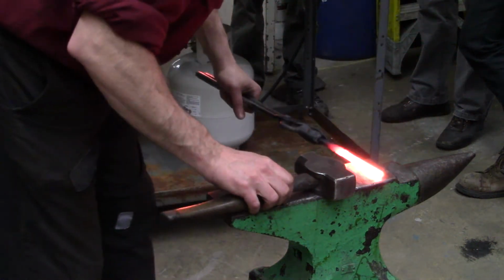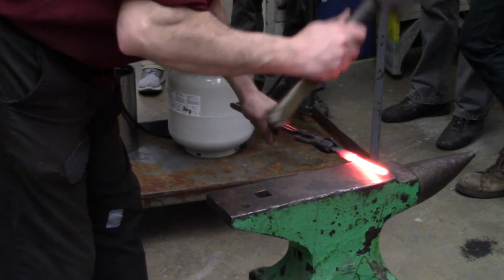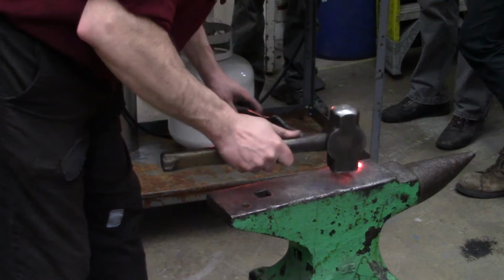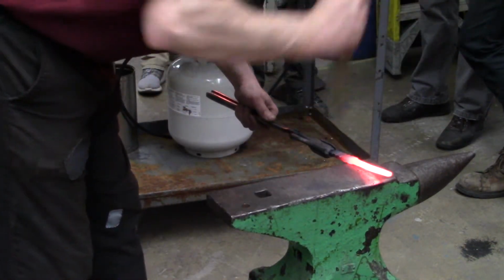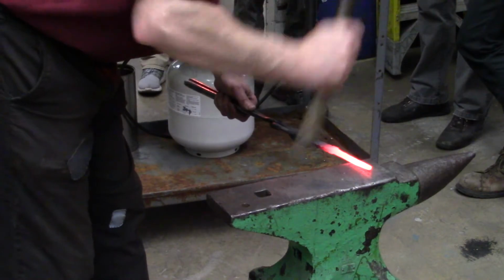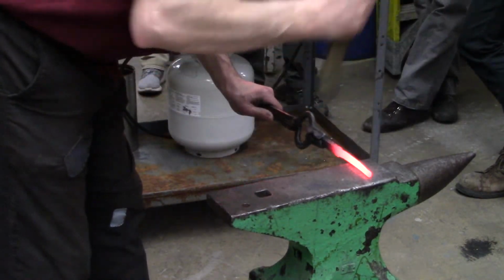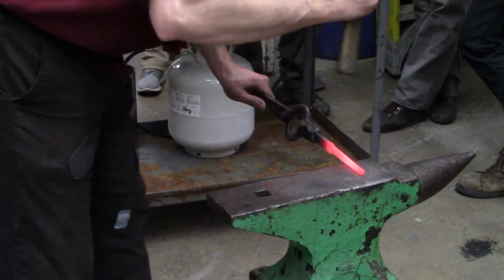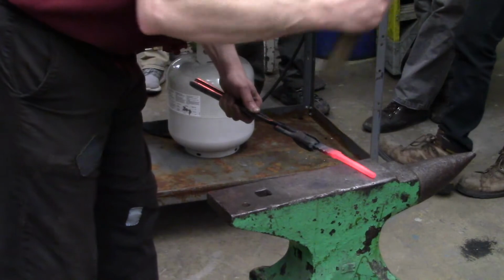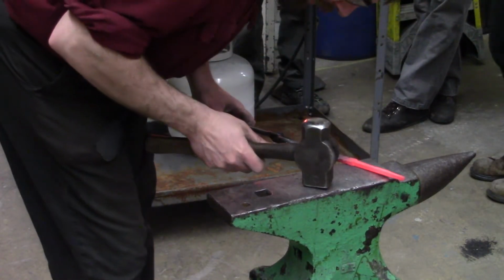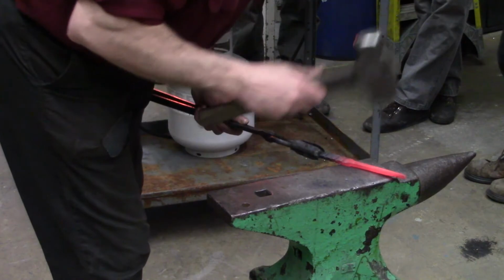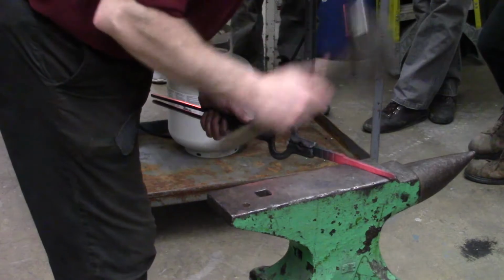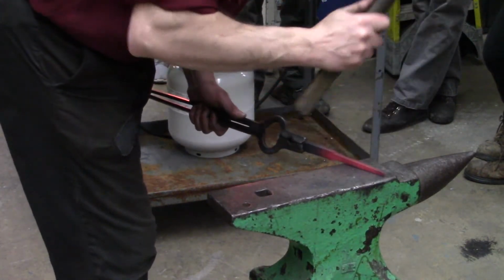The nut that you put on the back, what you normally do is you counterbore. The nut looks like it's a round nut. I have one I put in here, it's a round nut. But it has to screw down. Eventually, the rod comes up and gets in the way. So you have a screwdriver notch that goes around that.